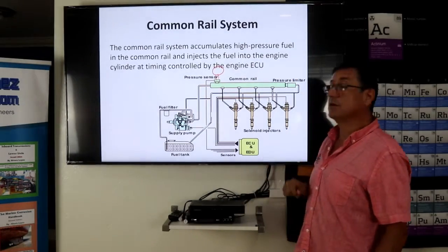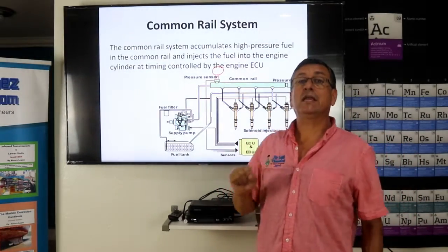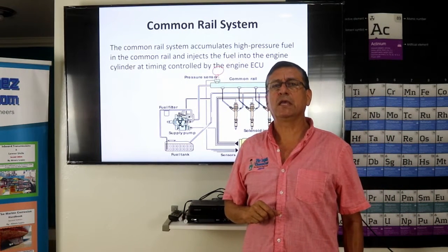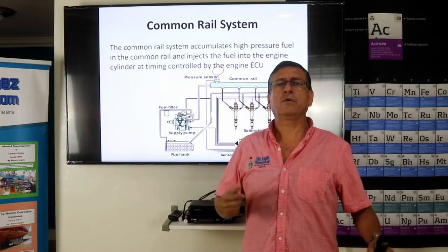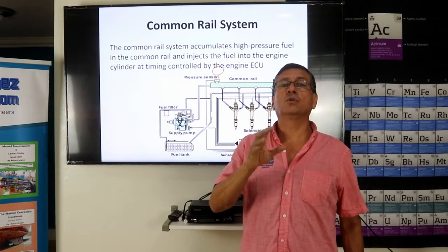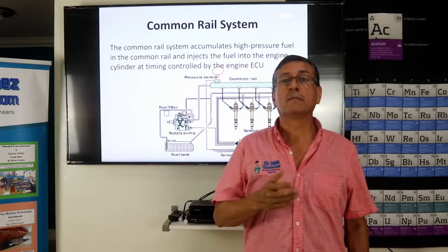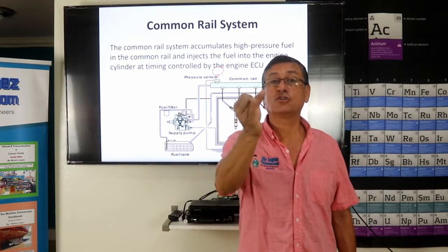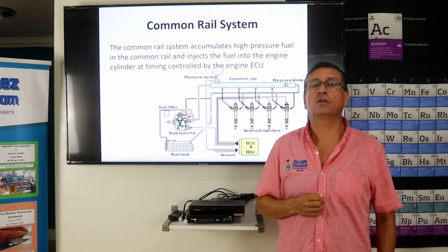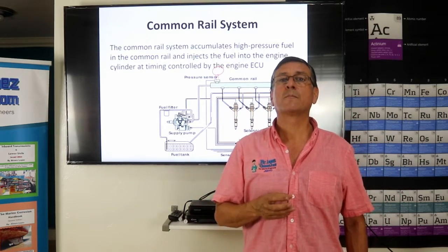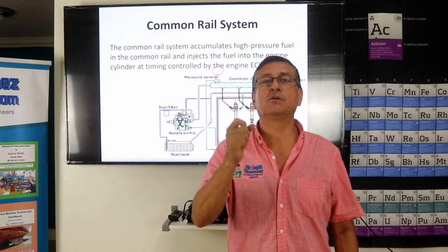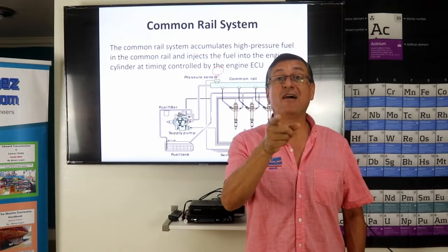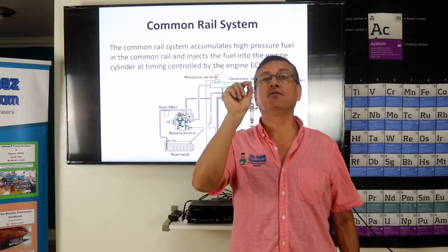There are a lot of sensors talking with the computer in order to control the fuel. Can you tell me a couple of sensors that work together with the fuel systems? Yeah, the throttle position sensor, one. Other one, oxygen sensor, important. Other one, manifold absolute pressure sensor, MAP sensor. Other, MAF sensor, mass air flow sensor.